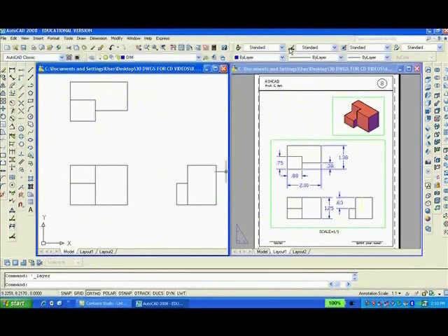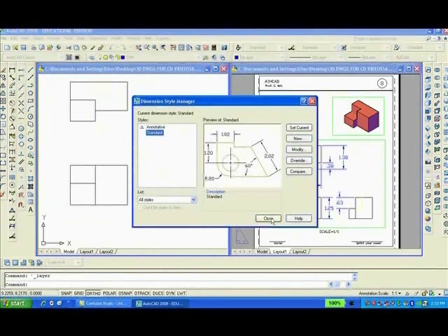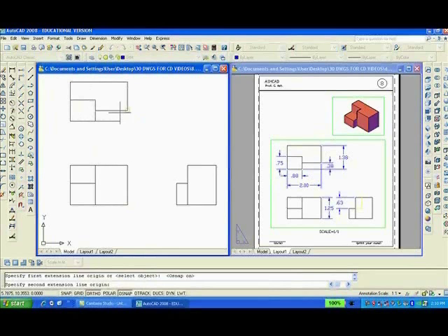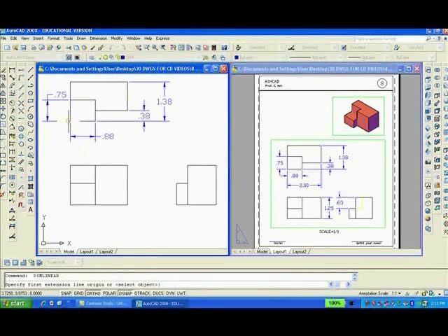And it's two places, so let's just see what dimension styles shows. It shows two places, so we're all set. So now I suppose I can start dimensioning with linear dimensions. OSnap has to be on. So I'm going to go from here to here. Hit the enter key. Here to here. That looks right. Here to here. Here. So far, so good.